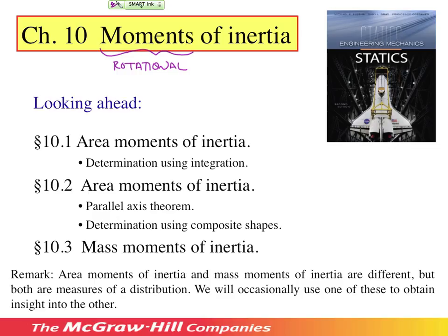Mass is one kind of inertia, and it represents the resistance offered by a body to acquiring translation. The fact that mass is a scalar is an indication that a body offers the same resistance to acquiring linear motion, whether we push it in any one of three mutually orthogonal directions. Rotational motion, however, is not so simple. Only a perfect sphere offers the same resistance to acquiring angular motion about any of three mutually orthogonal axes.